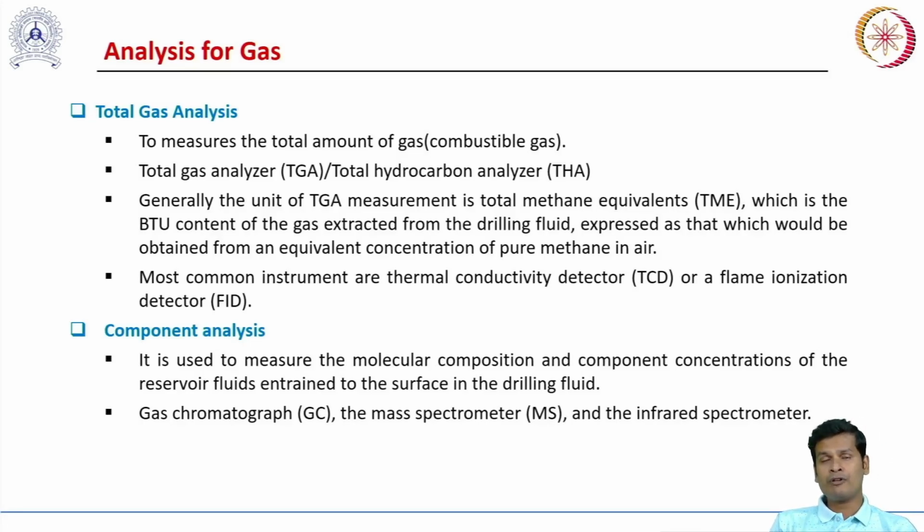Also, if you are drilling through a gas bearing formation, then the gas bearing formation will bleed some gas inside the drilling fluid. So again some hydrocarbon gas will be there inside the drilling fluid, which could be analyzed. So in total gas analysis, we want to measure how much combustible gas or hydrocarbon gas, which could come from a hydrocarbon bearing formation, is present inside our drilling fluid.